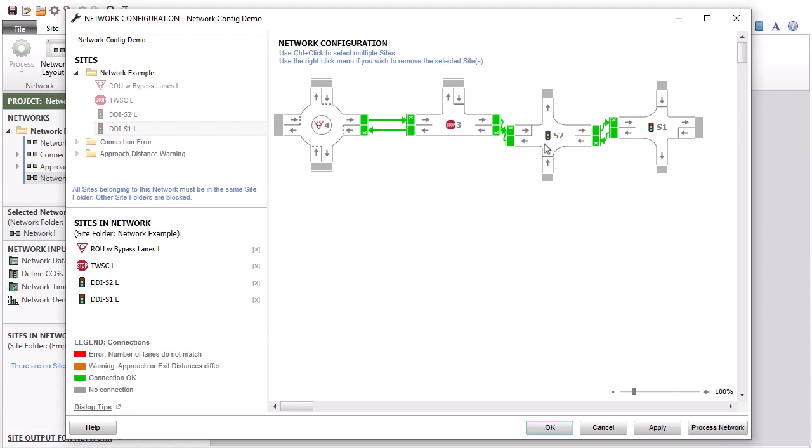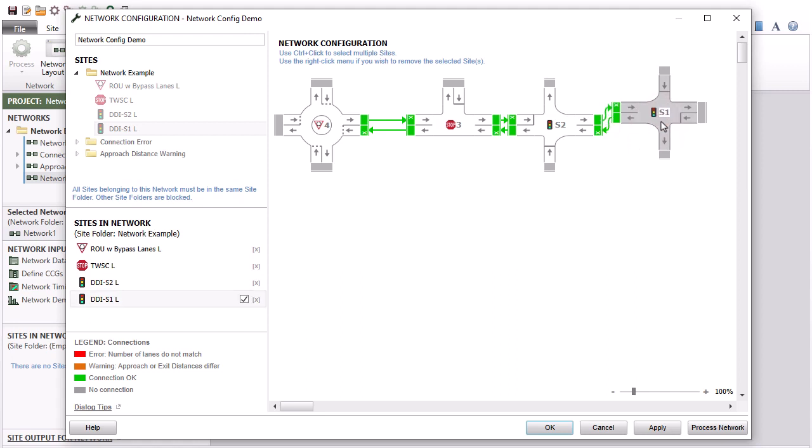When aligning a site with an adjacent connected site, the pictures will snap into position. For moving the site pictures more smoothly, press the Shift key, then click the site picture and move it slowly.